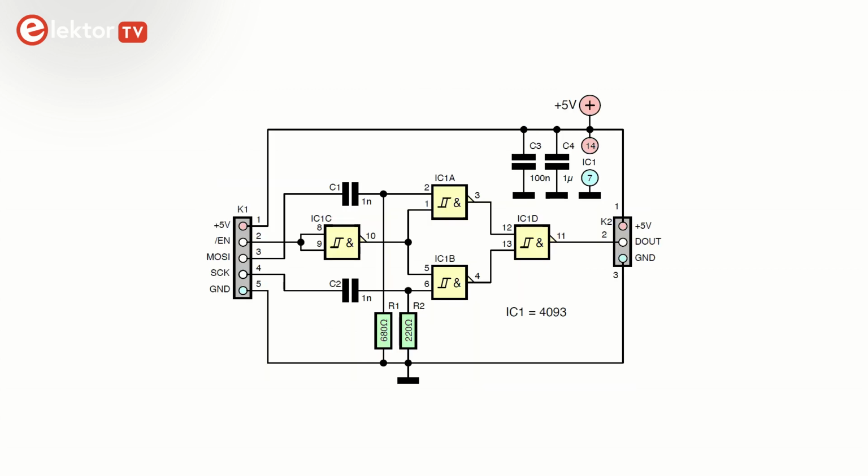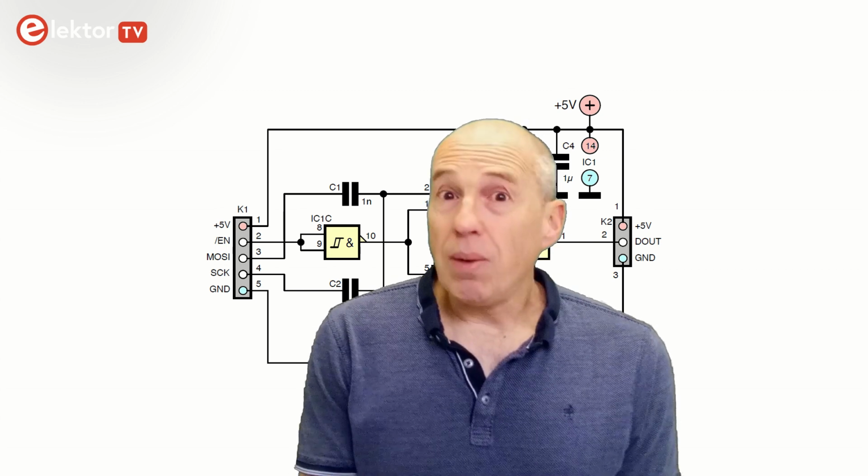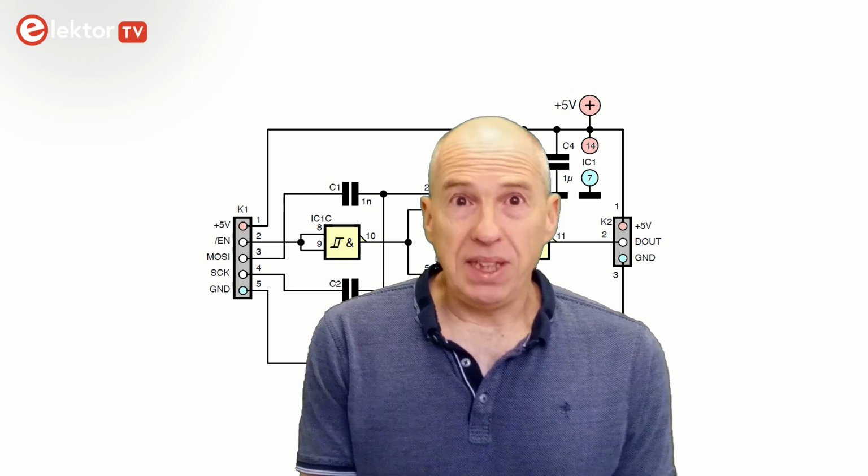I even designed a third circuit based on Schmitt-trigger NAND gates. This looks even simpler, but there are, of course, way more transistors involved. Now the pulses for the zeros and the ones are created independently from each other. SCK provides the zeros and MOSI the ones. The gate on the right merges them into one signal. This circuit only works in SPI modes 1 and 2. You could do something similar with monostable multivibrators.